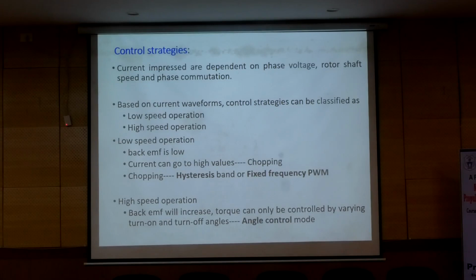here these control strategies, the current impressed depends on the phase voltage, rotor shaft speed and phase commutation, and based on this current waveform, the control strategies can be classified as low speed operation and high speed operation.